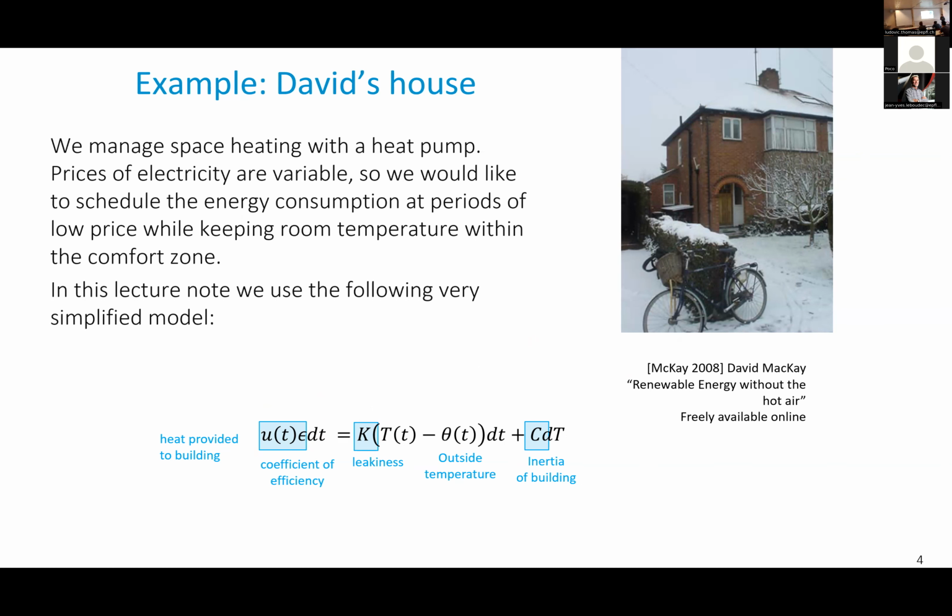And the interest of a heat pump is that this coefficient of efficiency is larger than 1, much larger than 1 if it's a heat pump with a deep ground system. Then for such a case, the coefficient of efficiency can be 4 or 5. If it's an air heat pump, the coefficient of efficiency is probably around 2. And if this is resistive heating, if you simply have radiators that burn the electricity in a resistance, the coefficient of efficiency is almost 1. It's close to 1.